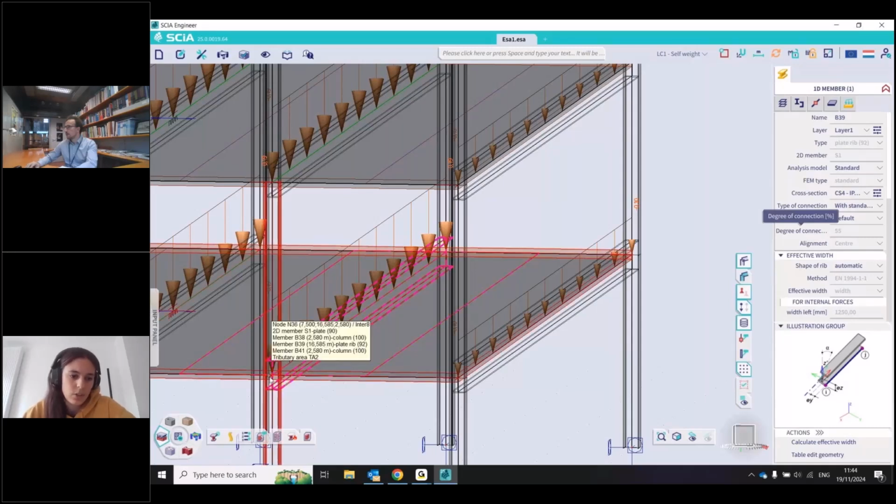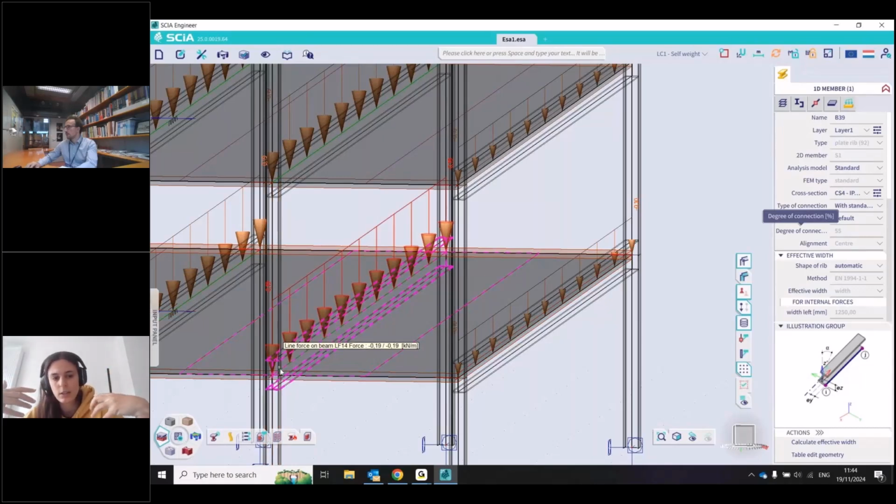So in the calculation, it will actually move this slab up for its stiffness calculation and move the beam down for the stiffness calculation to get the normal neutral axis. And also, if you then do a design at the end, the check for the composite beam, you will do the check of the composite beam with the neutral axis at the correct location that it will calculate itself.